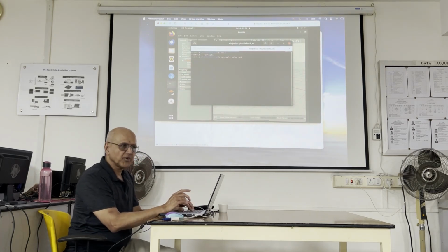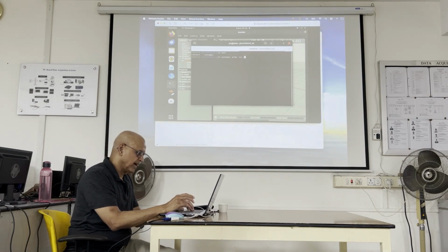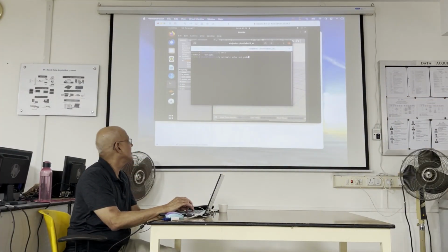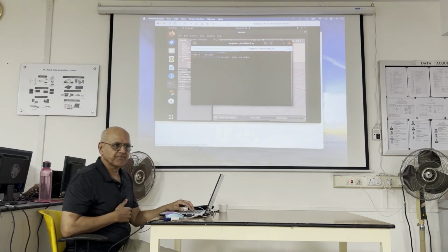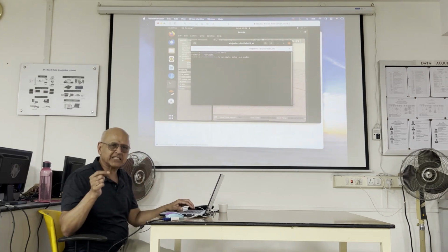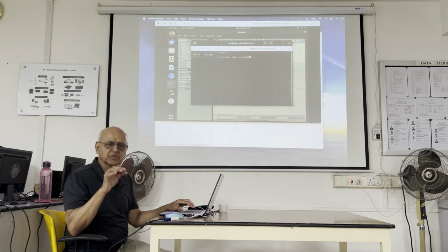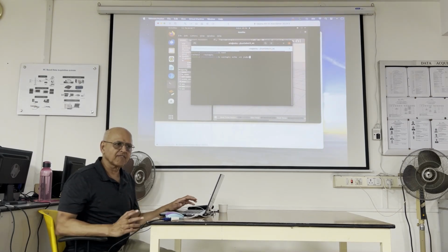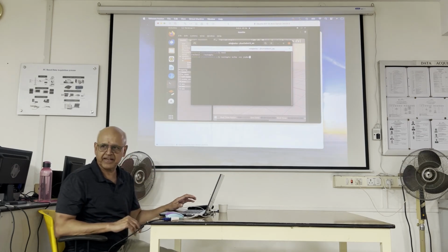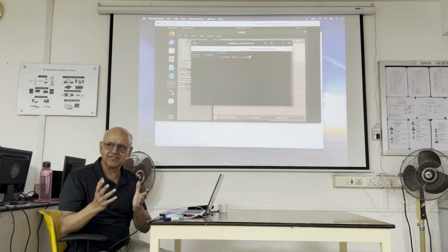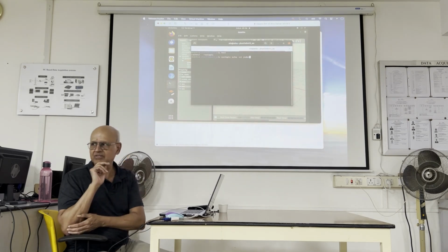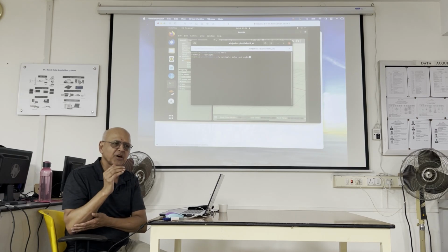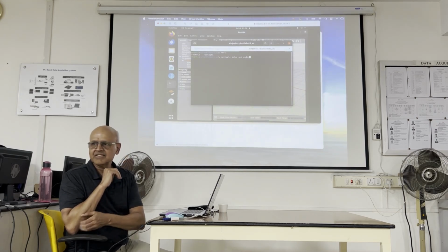And then you need the odometric topic. Now, I know it's /odom. I'm going to tell you later, how did I know? Because in a Ubuntu terminal, if you type ROS topic list, it will give you all the topics that this particular robot is associated with. And then you go to the ROS.org webpage or some other Google search page, and you can figure out what all these topics mean. I have done all that for you because I have worked on this for 12 years now. I know /odom is the odometric topic. So you can take it from me.